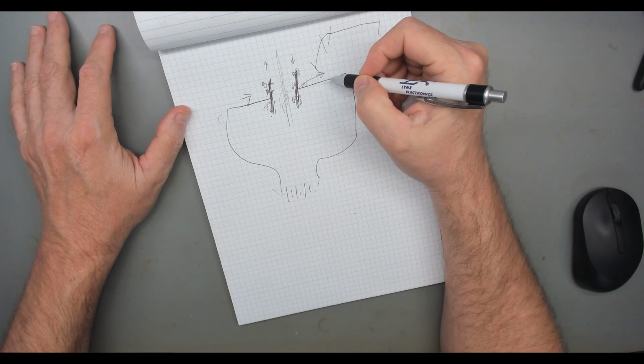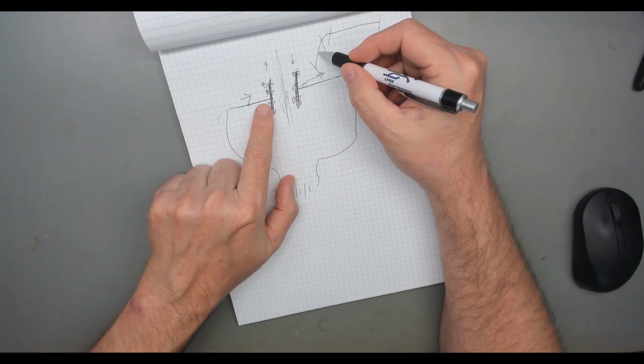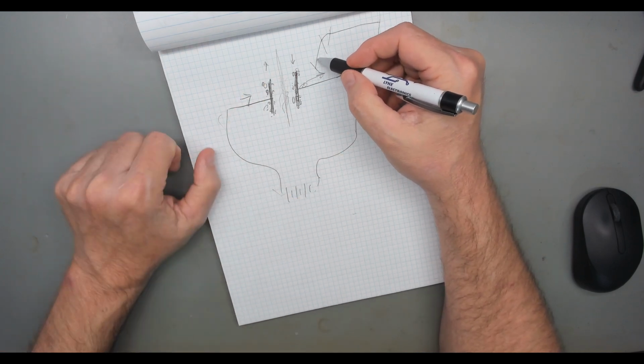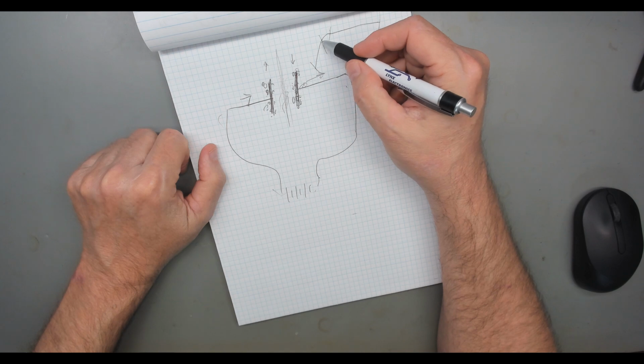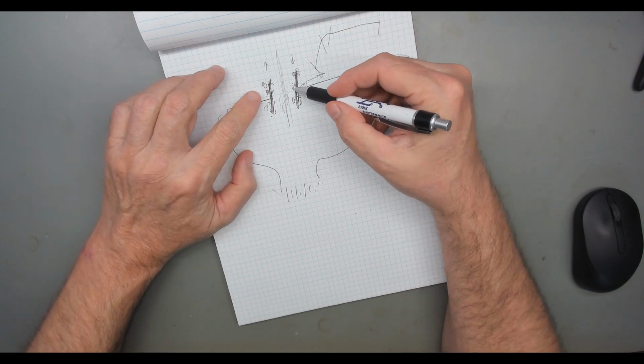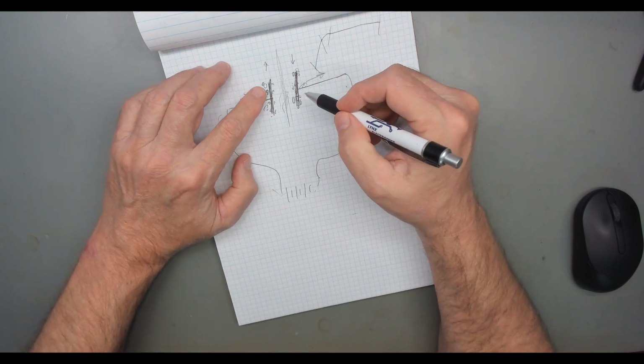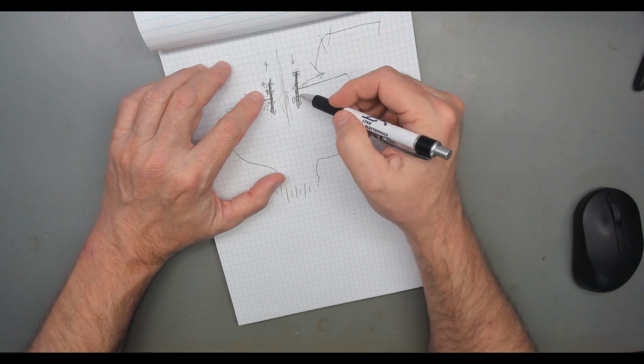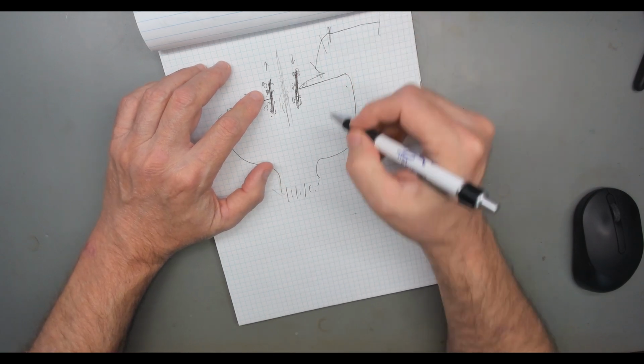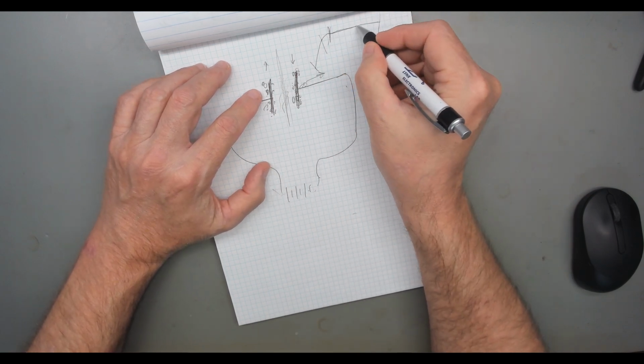You're going to have current flowing in this circuit as the voltage builds, as the electrons move and pack on this plate. Voltage is going to increase, and when the electrons have moved from here to where they're matched by the voltage of the battery, it's going to hit the battery voltage, and at that point it's going to stay there.